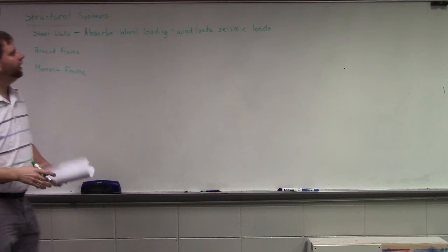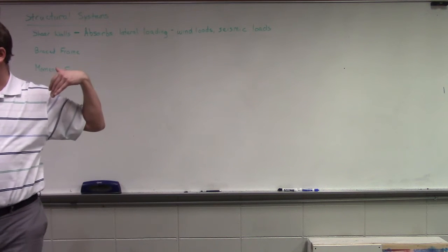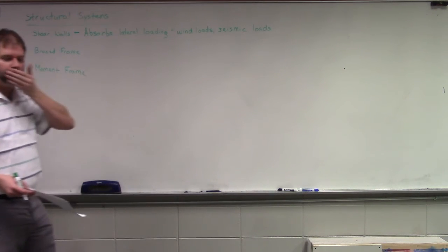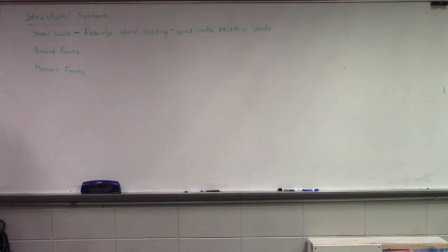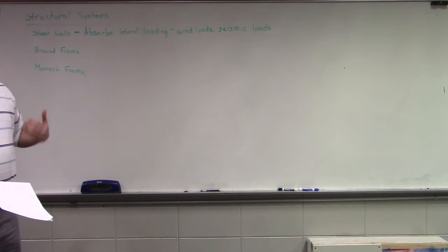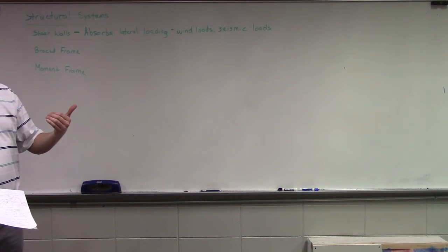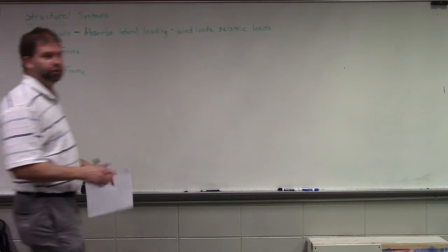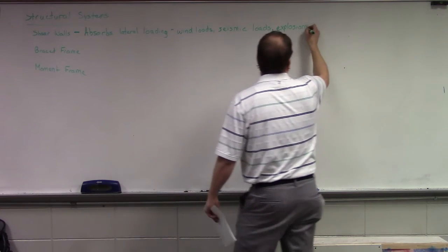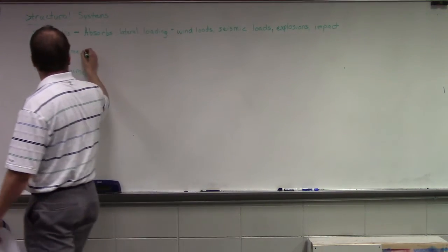While we don't have to worry about seismic loads, a portion of the wind load for us could be from the effects of a tornado, right? But that would still fall under the wind load. We also have to be mindful now that with some structures in the government sector, we may have to take into account things like explosions, or impacts. It's an unfortunate side of the times that we live in.